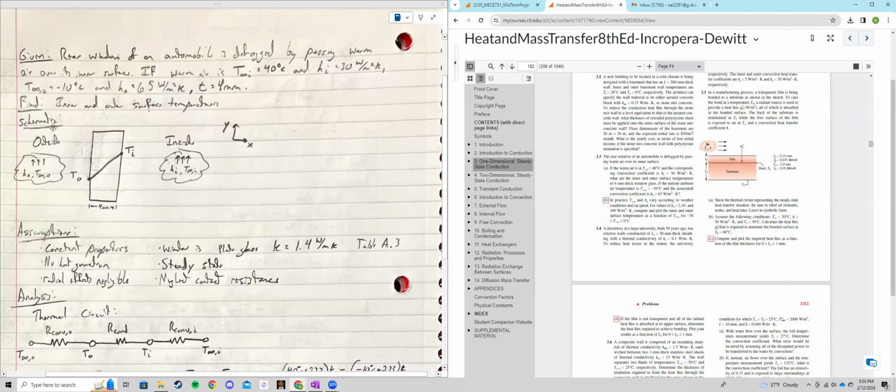So here in my schematic, I have labeled the outside, the inside, and in this rectangular box right here is representative of the glass. Specifically, its thickness is given here in its dimensions. So here I drew that T_o is going to be down here, and then T_i will be here. This will make more sense later as we go through the problem. And then I just have a regular coordinate system here. To represent that it's convection, I have drawn little clouds over here that represent the h_o and T_o, as well as inside h_i and T_i.